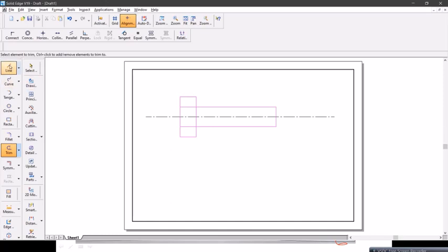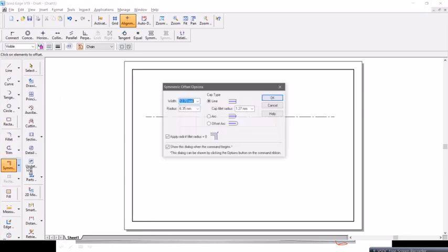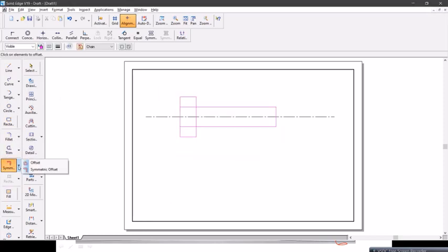We need to draw the nut. The nut has to be placed in the threaded length only, not beyond threaded length, because the nut has internal threads and you have an external thread over the bolt. The nut has to be assembled. Now offset distance as 50, single.